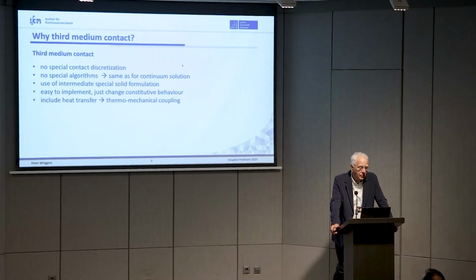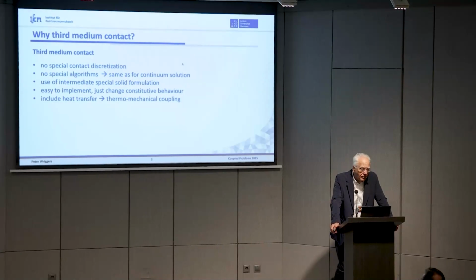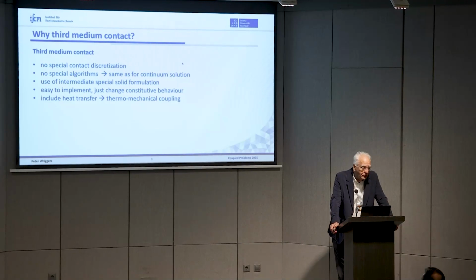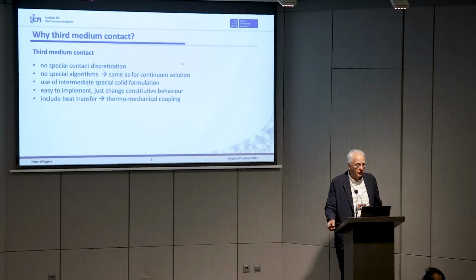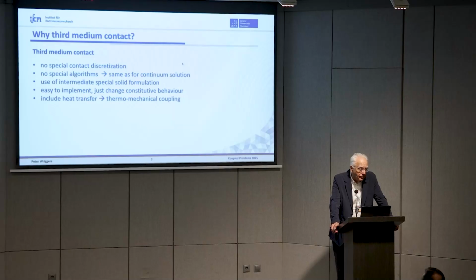Now the idea is to go into the third medium. First of all, you don't need any special contact discretization. You only have to throw in the third medium. You don't need any special algorithms. You just solve your continuum problem. You can use the third medium as a special solid formulation, which you do for large strain. Based on this, it's actually easy to implement. It's just like a new element with a little bit of twisting, but we will see how it works.